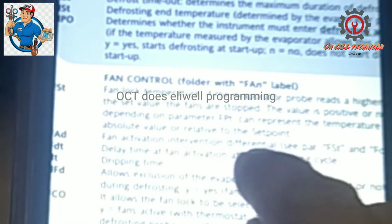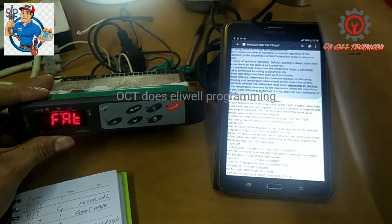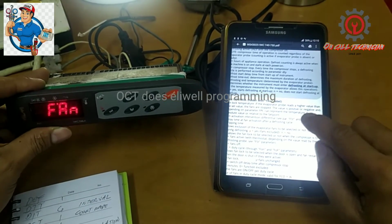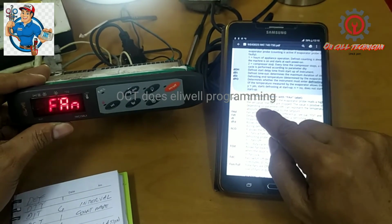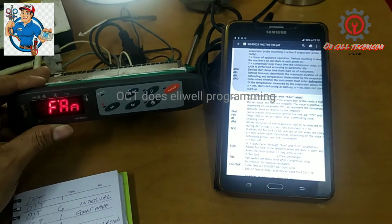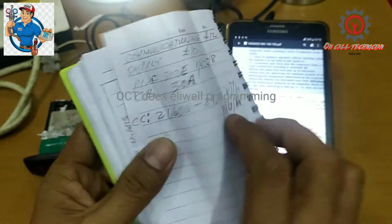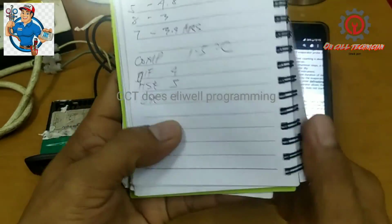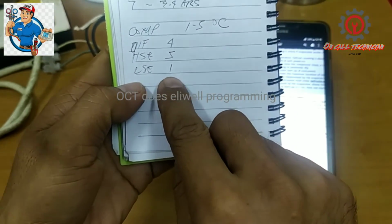If the evaporator probe, this one is the evaporator, if the evaporator probe reads a higher value than the set value, the fan will stop. And our set value is 1 degree.